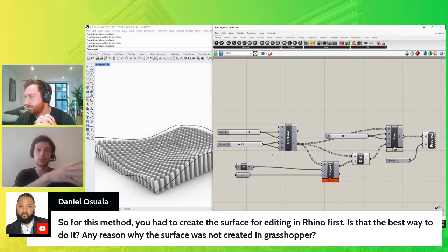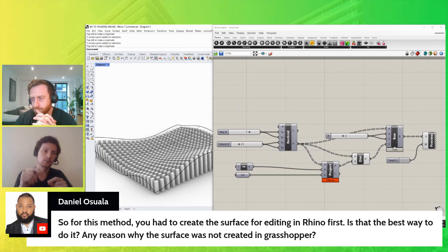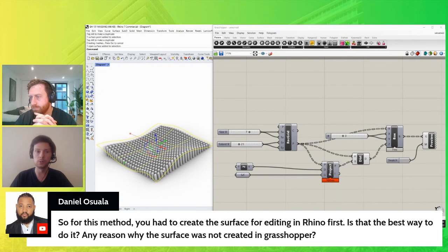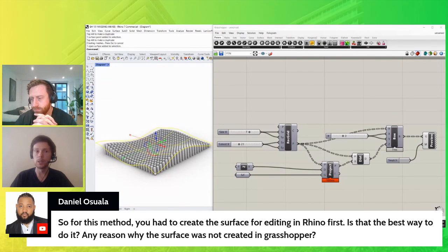Do you do these points in Rhino and then create the surface in Grasshopper from these points? Or do you generate even these points in Grasshopper? In this case, I have 36 points, each of them has 3 coordinates, X, Y, and Z. So I'd need all these parameters to define my one surface. It may become really complicated to manage and manipulate the surface. So in that case, it's a little bit better to have it visually in Rhino and manipulate it visually. I'm guessing in that case you're trying to design this sculpture, and then import it into Grasshopper as a reference.